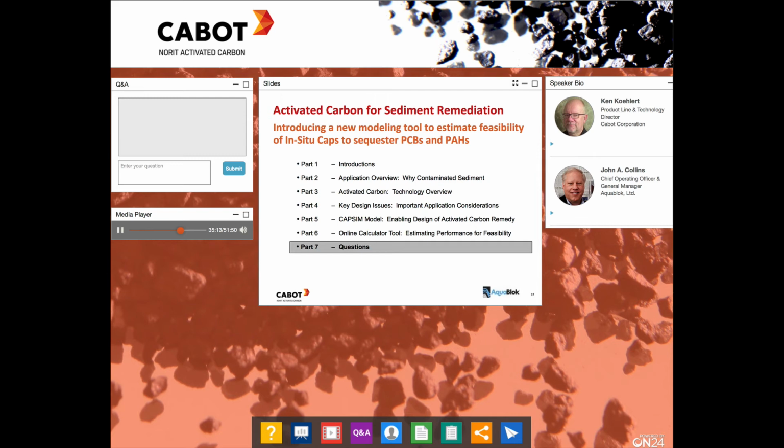Okay, we've got a question here from Matt about the grain size ranges for the GAC and PAC products. This information is available in the data sheets at sedimentpure.com, but our powdered product is a minus 325 mesh powder. The GAC product is a granule. It's minus 8 mesh, probably about 8 by 40 mesh size. So thank you.